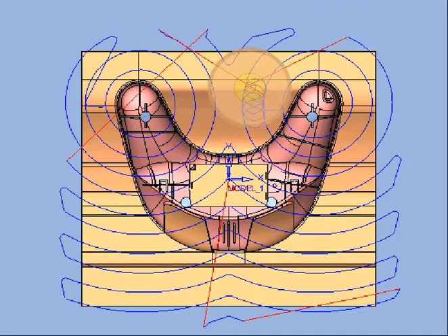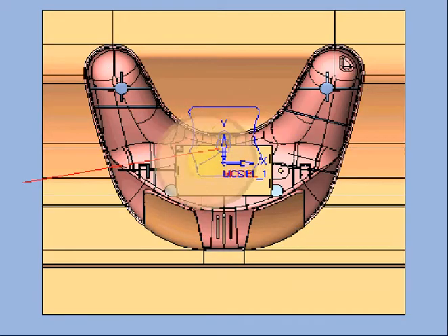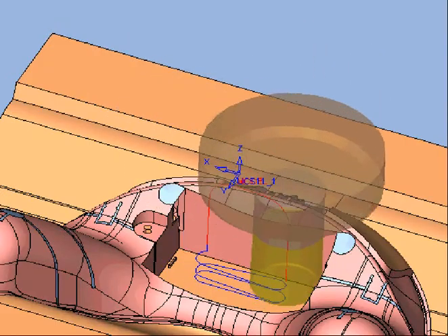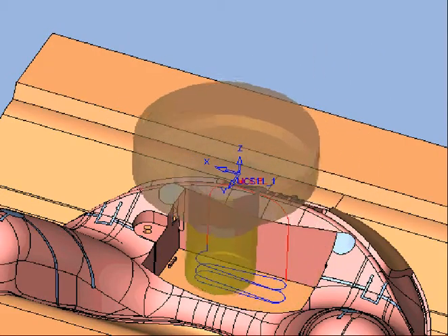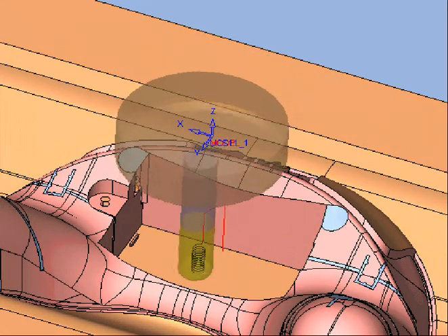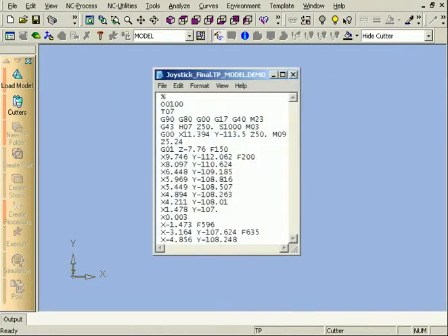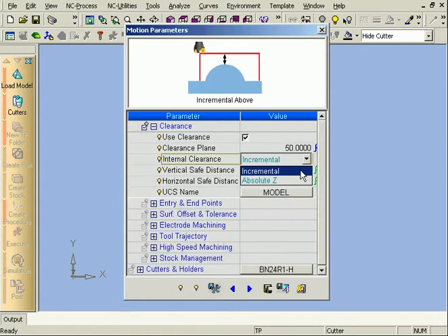Optimized cutting strategies include stock spiral, in-out, out-in, and adaptive approach and retract according to the specific stock. Adaptive plunge strategy is achieved by automatically selecting the plunge option, either tangent helical or Z, according to part geometry and actual stock remaining. Adaptive feed control reduces feed depending on the material removed or knowledge of remaining stock to maintain constant chip load. Air motion optimization optimizes clearance and is incremental according to actual remaining stock.